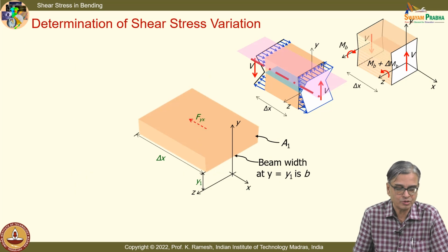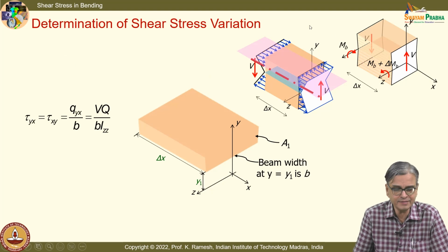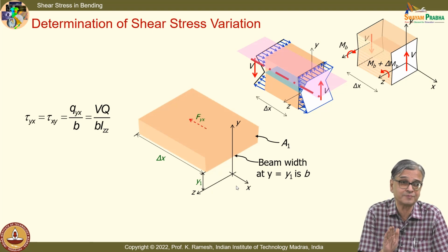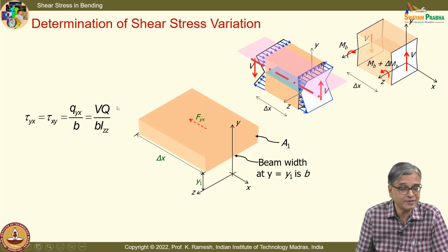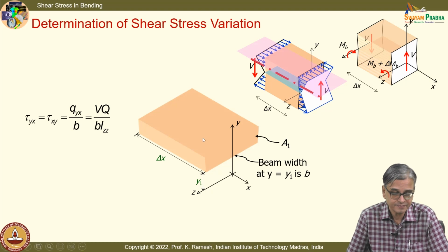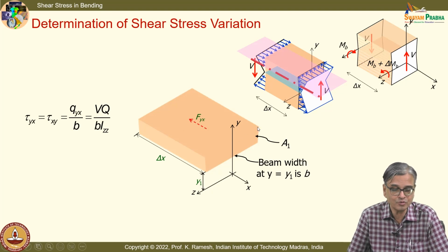And we will also illustrate in what way the flow happens. And here you understand and bring in, on the top surface, can I have any shear stress? Even though this cross section transmits shear force, we have said the shear force distribution should be such that it should go to 0. Can you tell me whether it goes to 0 on the basis of this expression? Can anybody see how it goes to 0 on the top layer? What happens to Q on the top layer?